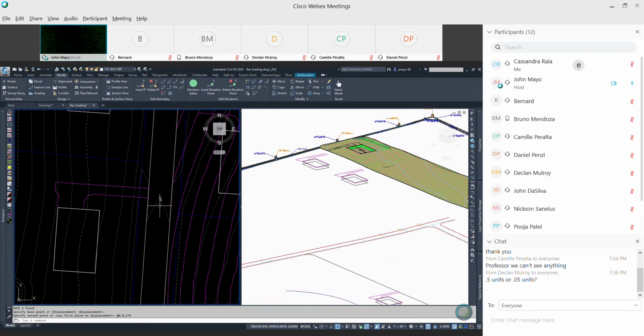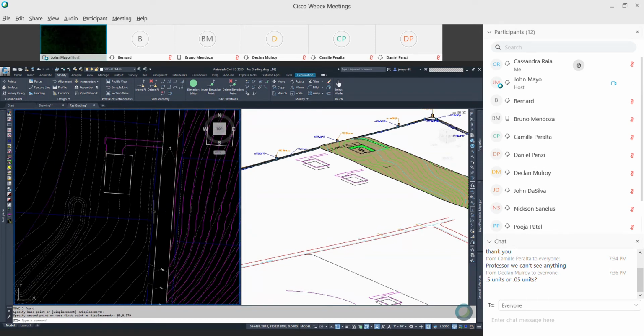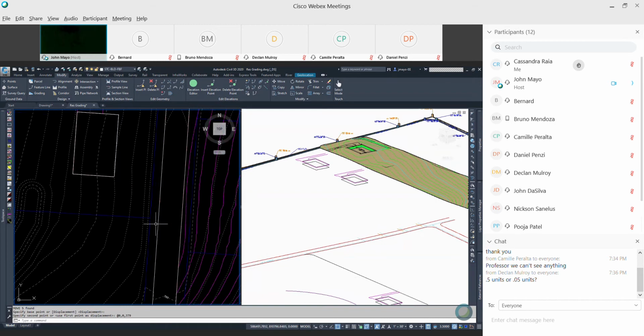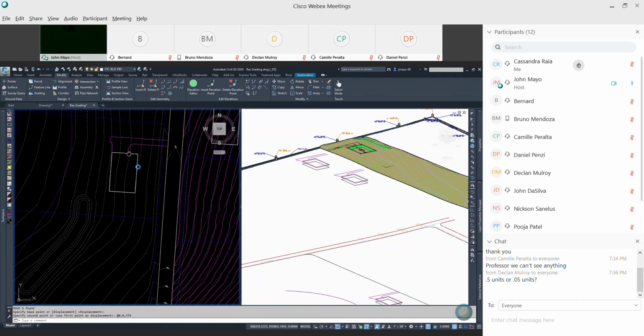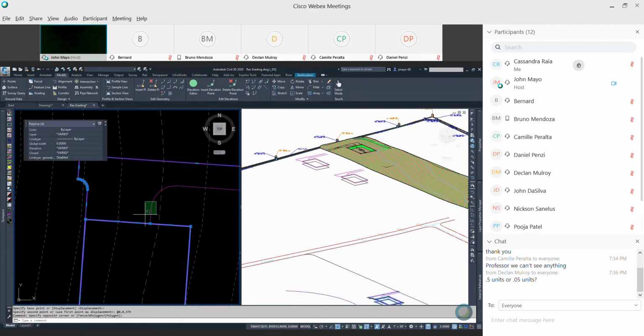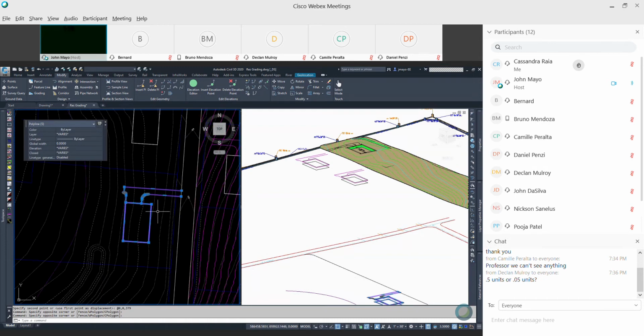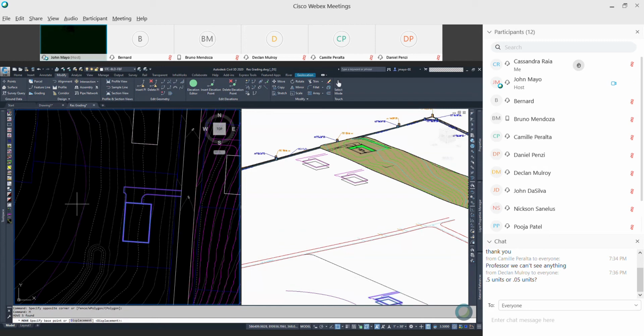And we're over here, 378, 380. This is like my low point, maybe 379. So I'm going to move these guys up to like 381. So I type move. It asks me for a start point. I click anywhere on screen, my second point.